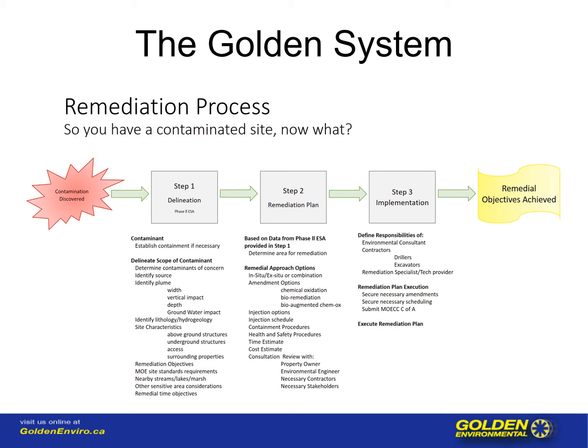We look at our injection options. What type of soil do we have here? Is the porosity very tight? Do we have lots of volume we need to put in? Is hydraulic conductivity high or low? We also look at an injection schedule. Certain ground types take amendments in certain volumes over time. So we look at injecting over time. How quickly can we inject? How quickly can we achieve saturation?